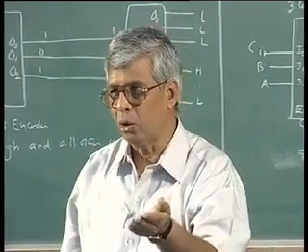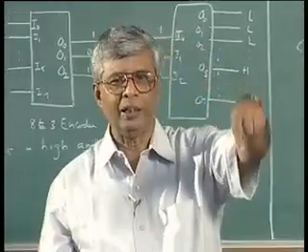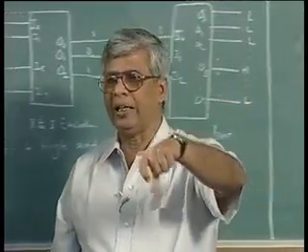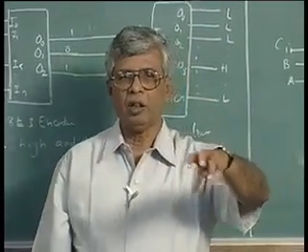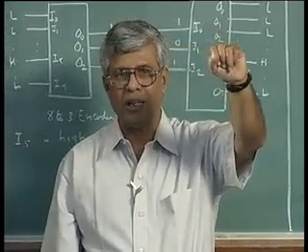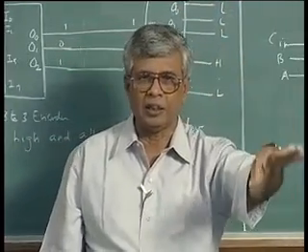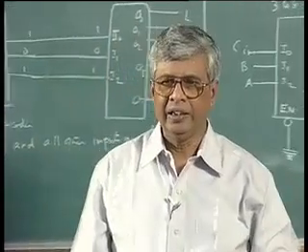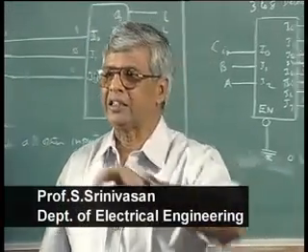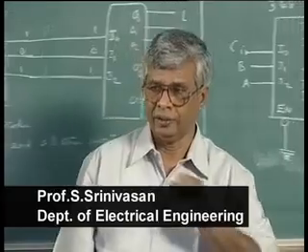When enable is low, it is equivalent to keeping it there, and when enable is high, it is equivalent to removing it so that it is not there. Electrically it is not there, physically you may have inserted the IC in a socket, but electrically you can ignore it.